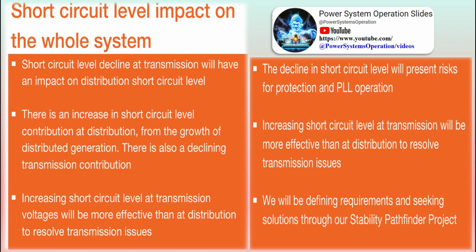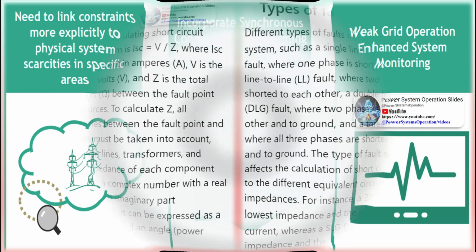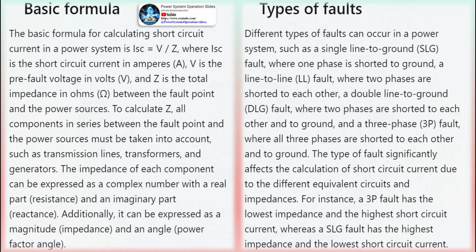Short-circuit analysis is performed to determine the currents that flow in a power system under fault conditions. If the short-circuit capacity of the system exceeds the capacity of the protective device, a dangerous situation exists. Since growth of a power system often results in increased available short-circuit current, the momentary and interrupting rating of new and existing equipment on the system must be checked to ensure the equipment can withstand the short-circuit energy. Fault contributions for utility sources, motors and generators are taken into consideration.